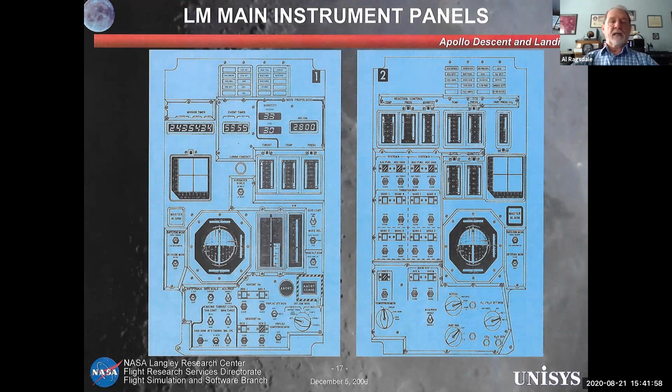So typically, when we had to abort, you would abort by pushing that and fire the descent till it ran out of gas to make sure you had plenty, and then push the abort stage button, and it would stage and then fly its way into orbit. There was a host of other switches, but those were the important ones.